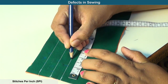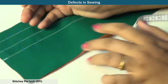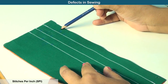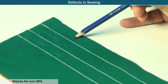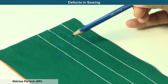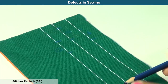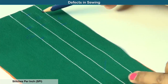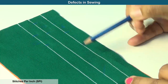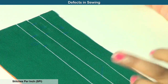1, 2, 3, 4, 5, 6, 7, 8, 9, 10, 11, 12. This is 12. So we made 3: 12, 10, 6. The SPI for 6 stitches is 4. The SPI for 10 stitches is 2.5. The SPI for 12 stitches is 2. So this is the preferred one. We should get 10 stitches. That is 2.5. You have to keep your stitch style at 2.5.